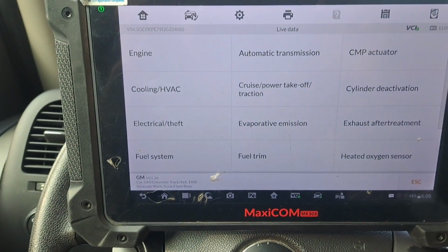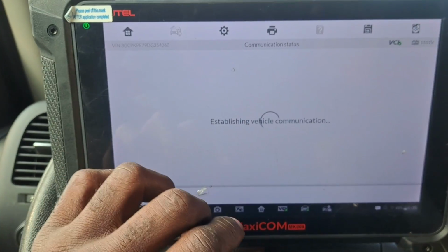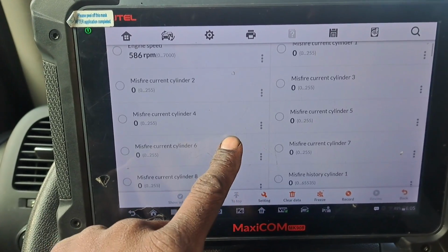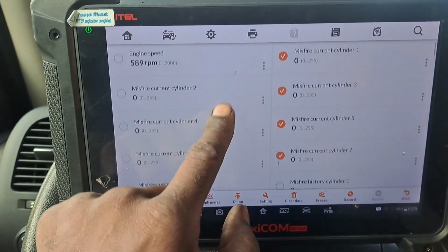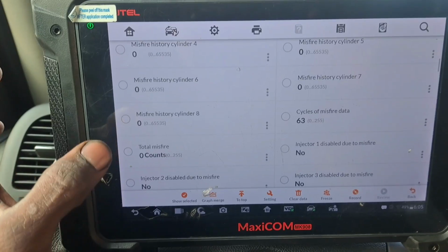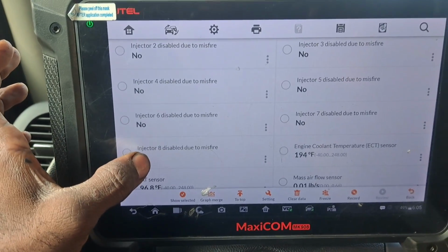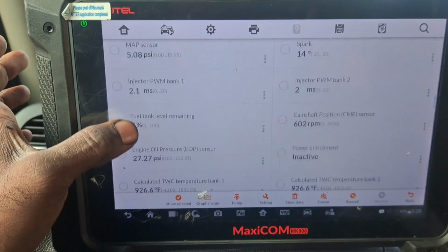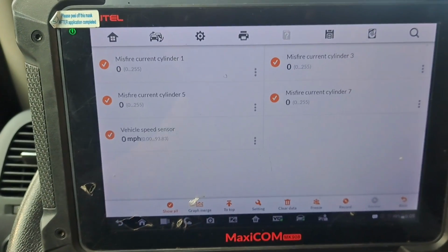So what I'm going to do, I'm going to drive it again because I got to get some gas, and I'm going to try to get this misfire captured if it happens during this drive cycle. And then I'll get some screenshots. Like I said, it's only on those. I'm just gonna get the odd bank, since that's the one we're dealing with. Like right now, it feels a little shaky. It could be because of motor mounts. It's not detecting a misfire or anything. Where's my speed? Did I pass it? There we go. So I'll try to get it and update.